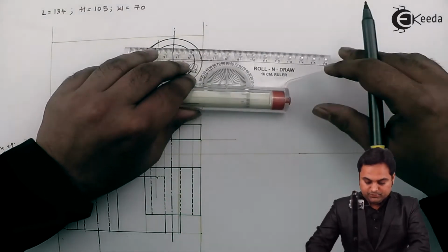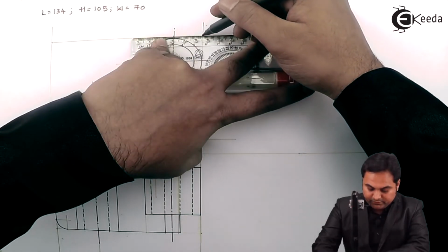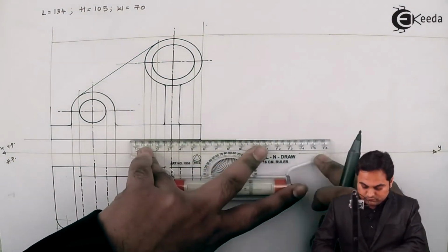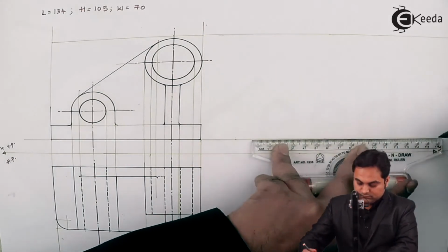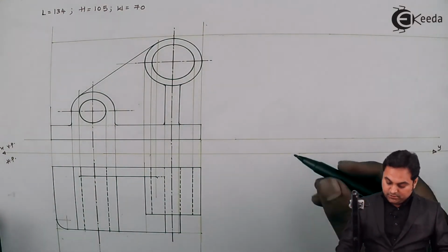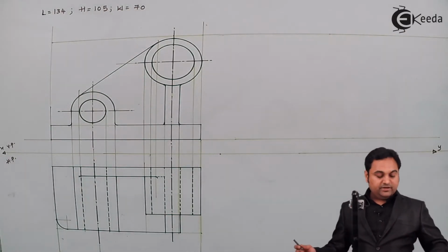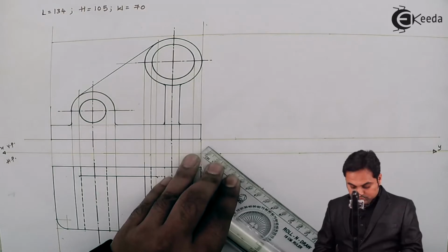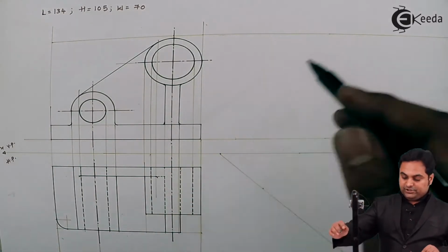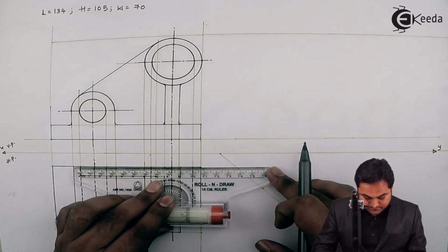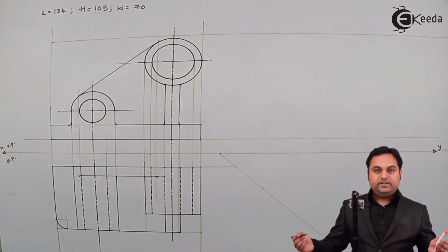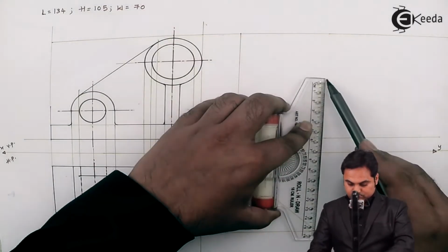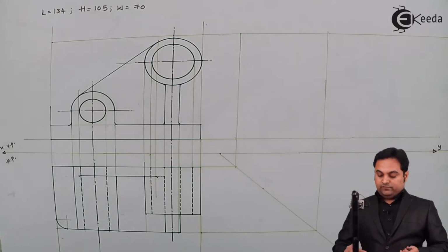Let us get started here. Now I am projecting the height with the help of light horizontal line. So this will be the height for the side view. Next, for the width, here I am selecting a point and marking 45-degree angle. Then projecting the width upwards, taking it up to this 45-degree line. So this is the width which I have projected.